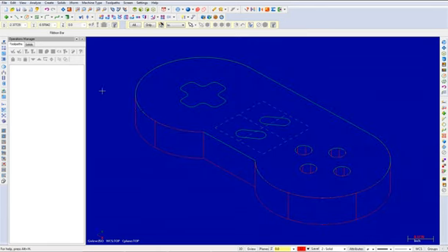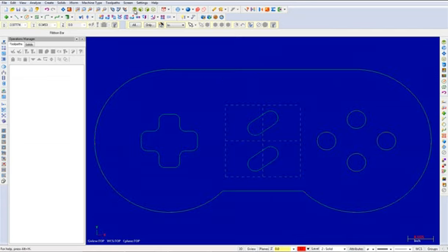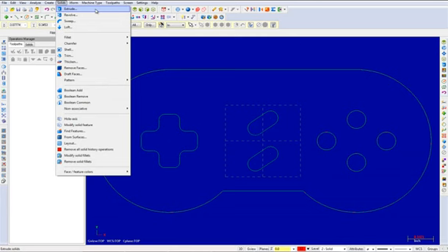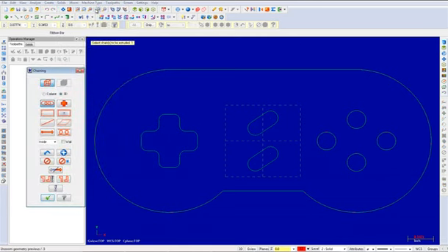Now from the graphics view, choose Top. We will now cut the shapes. Again, select Solids, Extrude. When the chaining dialog box appears, leave the default settings. Now select the following chains in the clockwise direction as shown. Once complete, select the OK button to exit the chaining dialog box.